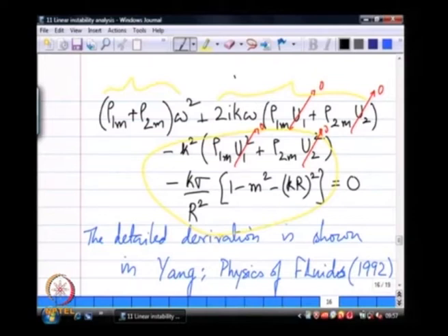So, if I go back to this full 3-dimensional equation of a quiescent cylinder of liquid of radius r in a fluid of density rho 1 with the inside fluid being rho 2. This is essentially the surface tension part of the instability, that is the only part that matters, the densities do not matter. If you look in this red equation here, remember we simplified the previous more general equation by setting rho 2 equal to 0. And there is a rho 1 inside here. Okay, so, essentially the fluid density and the surface tension of the fluid are the only parameters that matter.